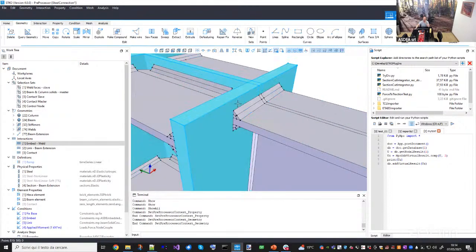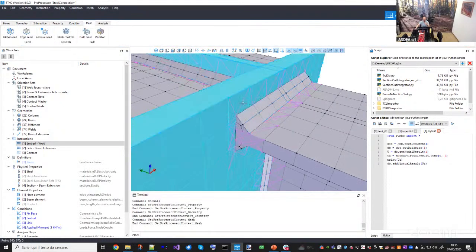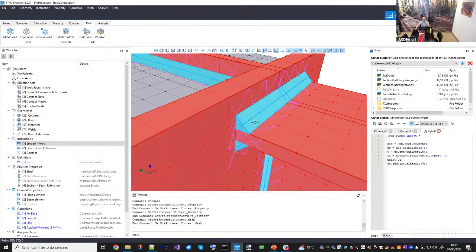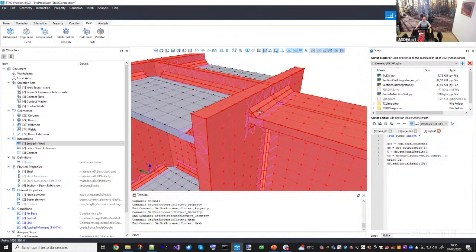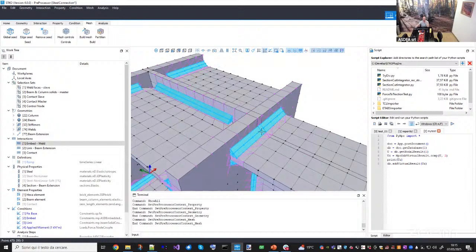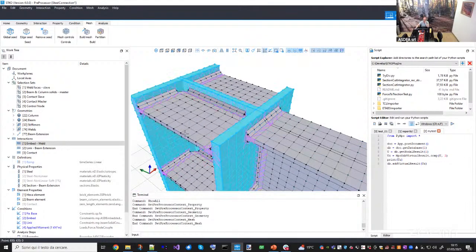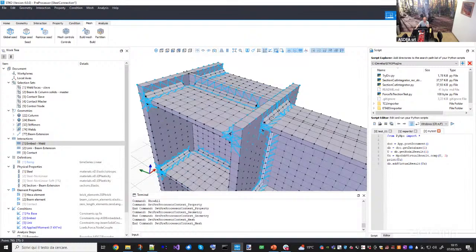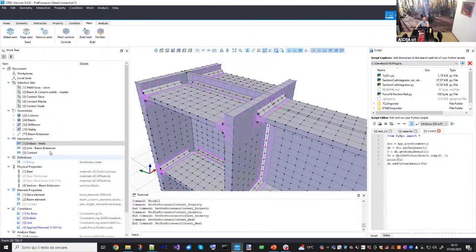the mesh should be compatible. So if you want to refine, for example, the welds, you will have to refine also the confining geometries. But this is not necessary, okay? So here I decided to keep them separated and use a particular multi-point constraint to attach them in such a way that I can have incompatible geometries between the column and beam and the weld itself. So I can use different refinement for the meshes. If you have seen previous webinar, you already know what I'm talking about, which is the embed condition.